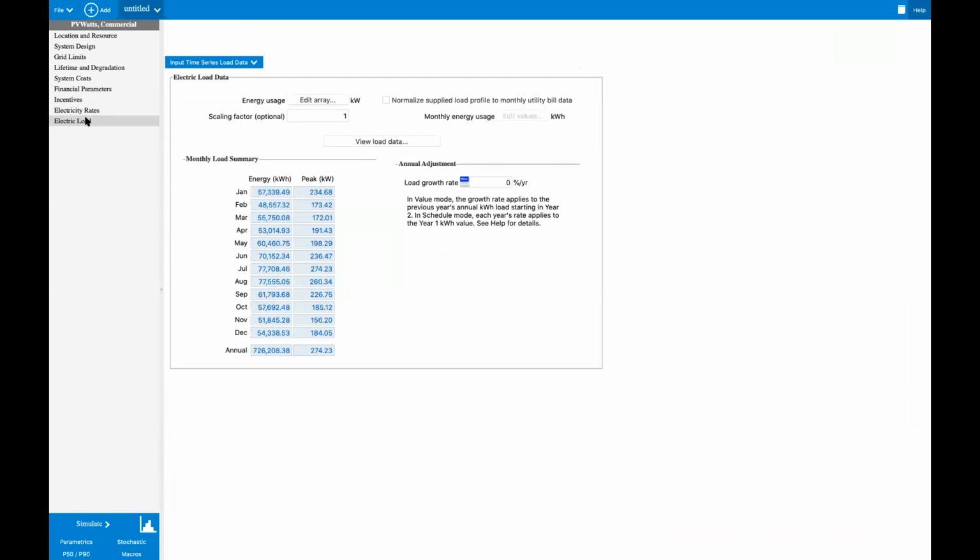Demand rates are really important to understand, especially when you're working with farms or businesses, as it relates to the overall financial impact of the project. And it's really important when you think about demand rates to understand your load profile, not just from a monthly perspective, but from an hourly perspective, because installing solar will not automatically decrease your demand.